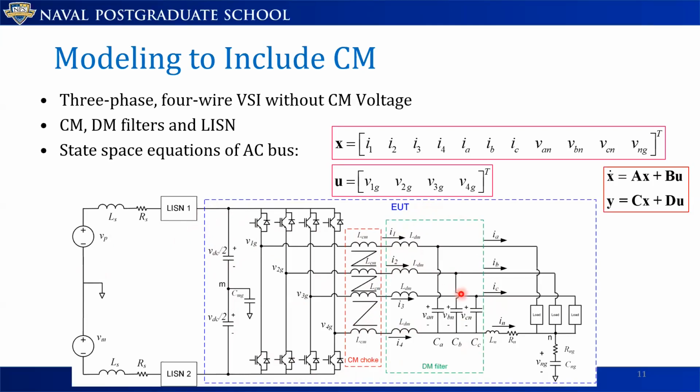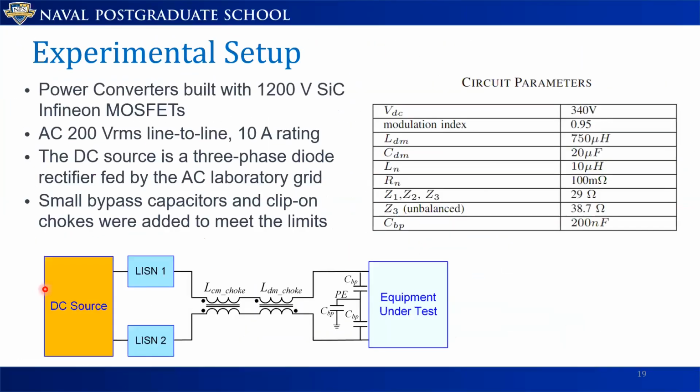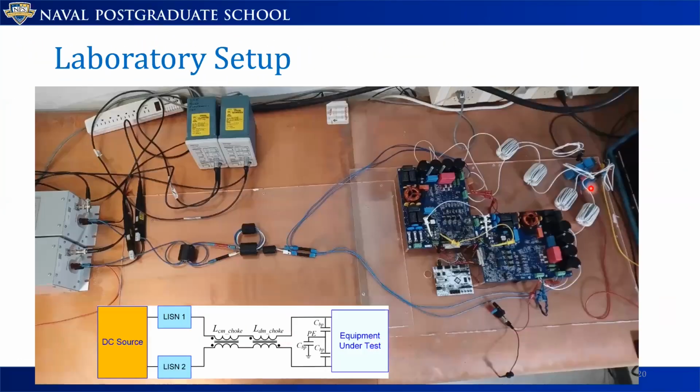Okay, all right, thank you for that. So the next question is, do you see any major differences between grid forming and grid following inverters in terms of potential EMI issues? Actually not. We don't see very much difference between the two as far as meeting the military standard limits. Most of the noise we were struggling with, as I mentioned, is at very high frequency due to the layout.